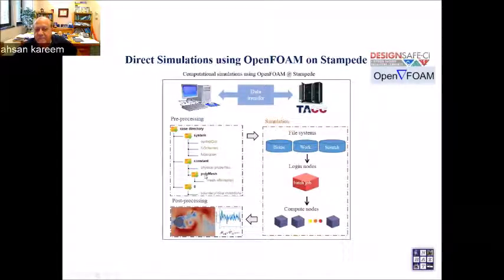These are the three basic system, constant and polyMesh, and the boundary conditions files, which you'll need to run the OpenFOAM code. Then as an expert user, you can go straight to Stampede, pick one of these files, system, and through that you log in, in batch mode, different nodes will run your operation, and you will get your results.